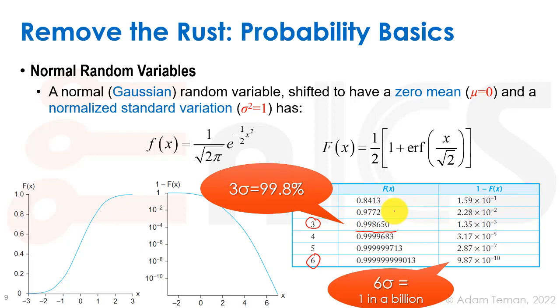Why is 3 sigma very significant? Because we usually set our process corners to be where 99.8% of the transistors are fabricated, and we take the worst case, if it's slower or faster, and that's where we set the parameters to figure out where most of our fabricated devices will fall. That's to get as high a yield as possible, to have as many of the things that we fabricate actually work. So that's why we take 3 sigma as the place where we put our global corners.